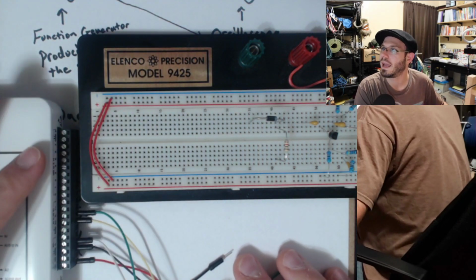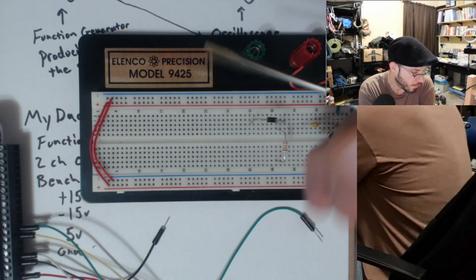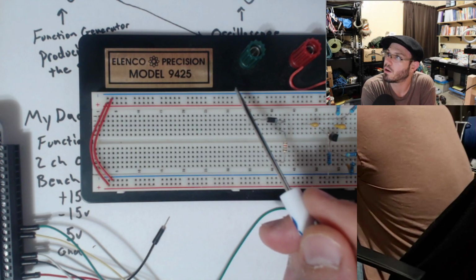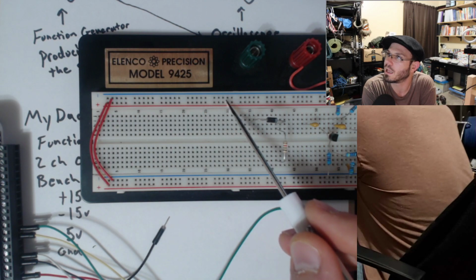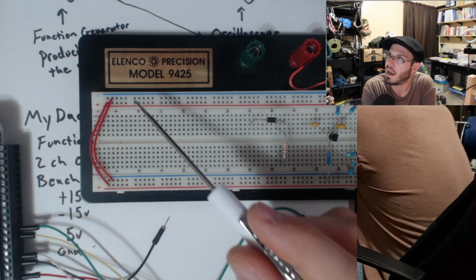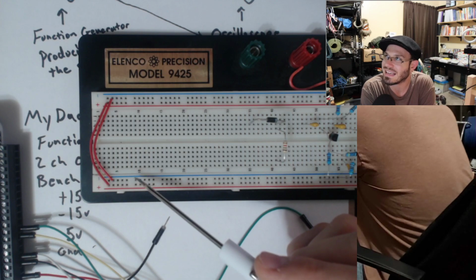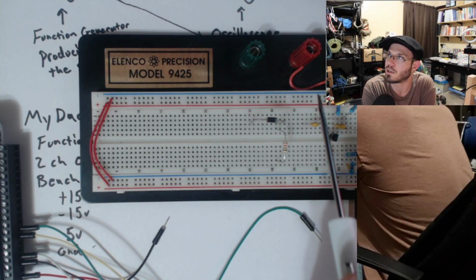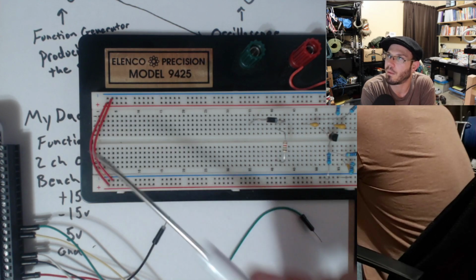And I'm going to set up my breadboard as I typically do. So over here you can see I have a minus rail that goes all the way across the board. I have a positive rail going all the way across the board below that. And then I've jumpered the minus to the minus down here so that I have access to ground on both sides of my board to make it very easy for me to place components, whether I need ground up here or ground down there. And the same thing for my positive rail.